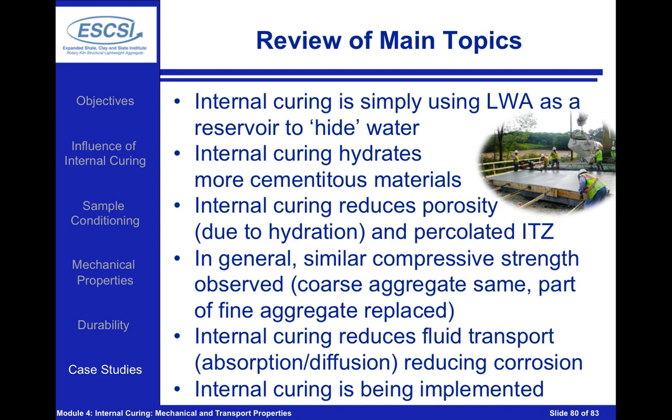So what we will see here is that we will typically depercolate the interfacial transition zones because we've taken sand out of the system and replaced it with a lightweight sand that typically doesn't have an interfacial transition zone. This will reduce transport properties because now we've got lower porosity because of increased hydration, and we have a reduction in the percolated transition zone.